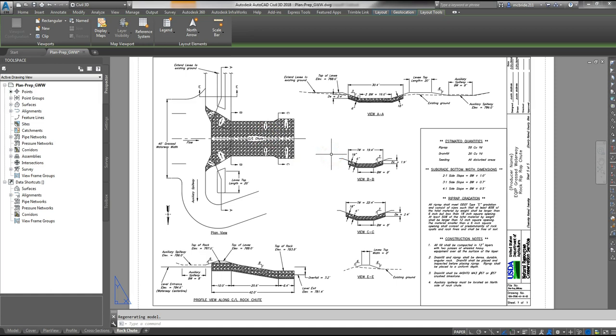There was really no other practices associated. You could have had a couple other things going on. Maybe you had, for instance, an underground outlet like a French drain, or you had a riser pipe that you had to put some kind of orifice on, or you could have had a different grade stabilization structure. You could have had, say, a concrete drop box. You could have had a rock pad, different things like that that you can add to these plans. But that's really dependent on the particular site that you're working on.